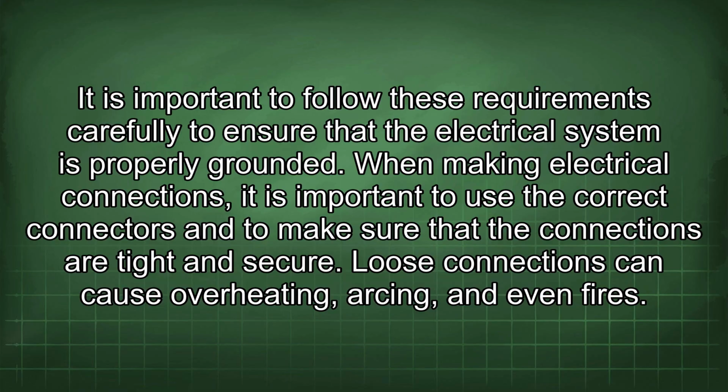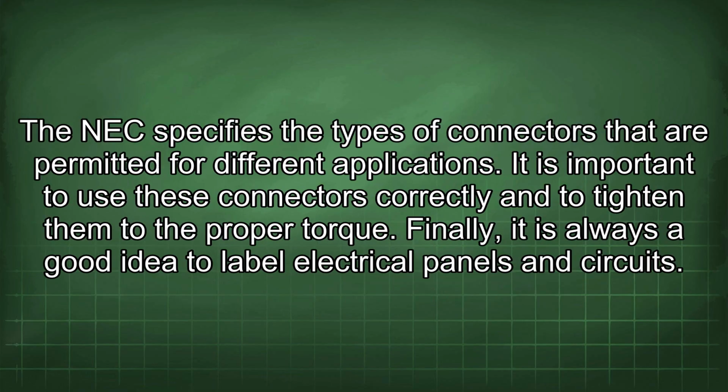When making electrical connections, it is important to use the correct connectors and to make sure that the connections are tight and secure. Loose connections can cause overheating, arcing, and even fires. The NEC specifies the types of connectors that are permitted for different applications. It is important to use these connectors correctly and to tighten them to the proper torque.